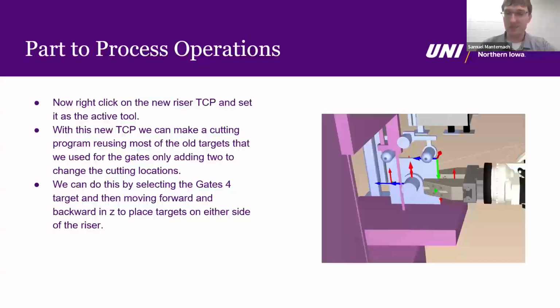You'll see it's located in the image on the right. You have our approach point where we located it behind that riser. You can create a cutting location there. And then if you move the part forward in Z, you can locate it beyond the cut, between the end of that riser and the start of our gripper, so you can get the second cut location.